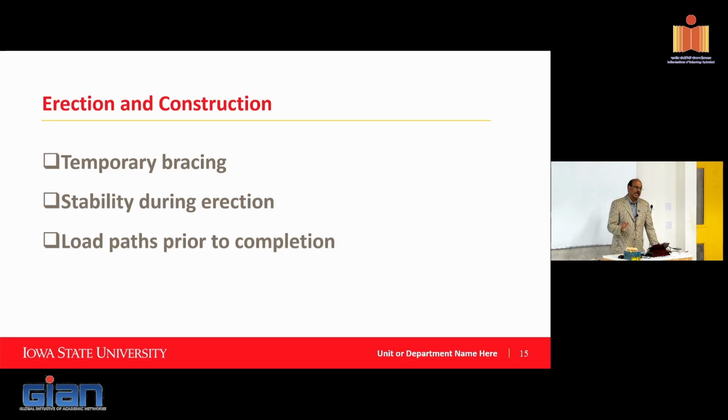But then, if a cyclone happens to come by, you don't want to lose the structure. So there are requirements to make sure there's a clear load path. If the structure is temporarily supported, it can still survive some small level of earthquakes or wind load so that you don't lose the structure.